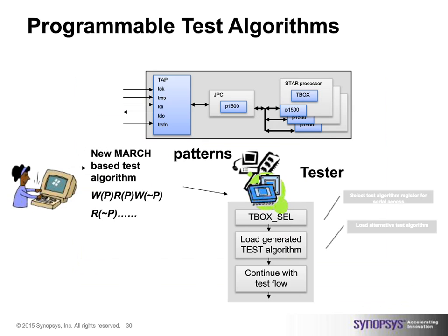The good thing is that the STAR Memory System does have also programmability in it. That is, you can come in from the JTAG port of the chip through the server, to the processor, and update the algorithms that sit in the processor. So the programmability is important in order to allow you to modify the test sequence itself or the test algorithm, either for different corners or for debug and diagnosis purposes, for upgrade purposes, and also to change the loops if you want to count the loops 4 times versus 7 times versus otherwise. You can do that whole thing via the programmability.